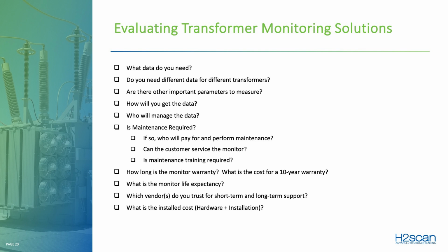Also, how are you going to get the data? Are you going to put an alarm contact into SCADA? Are you going to bring back the real-time data? You're going to aggregate all that data for all your transformers, use AI to do your own analysis. There's a lot of options today, and a lot of utilities actually have people who will manage that data. So if you're not somebody that has somebody that is set up to manage that data, that can be an issue. So you need to understand how you're going to get the data and who's going to be responsible for the data.